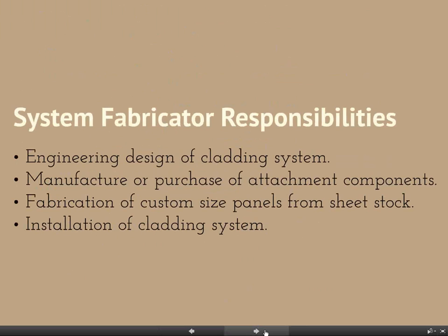Okay. So the fabricators, what are they going to do? And I think that we did have a question about talking about shop drawings. Fabricators, we're going to assign them the delegated design responsibility for coming up with the attachments to secure the cladding back to the building system, whether it's stud or masonry, and make sure that that design is signed and sealed by a professional engineer so that we don't have the cladding blowing off of the building and causing damage both to the building or anybody happening to walk by.